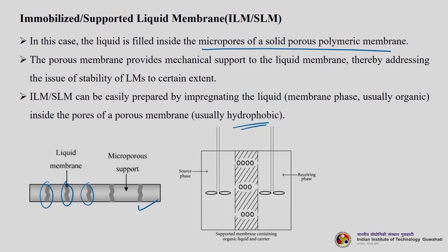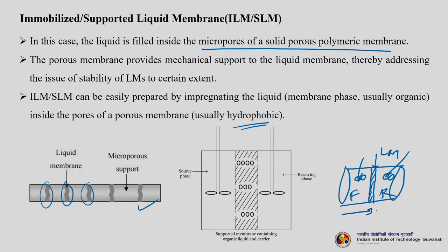So, you can have some sort of cell system. Here you can have your liquid membrane. So, this is the liquid membrane. You stir it, one side is feed, the other is your receiving or extract phase. We are stirring both sides just to enhance the rate of mass transfer. From here the components should move into the liquid phase, and once they come here they should also be properly trapped inside the receiving phase.